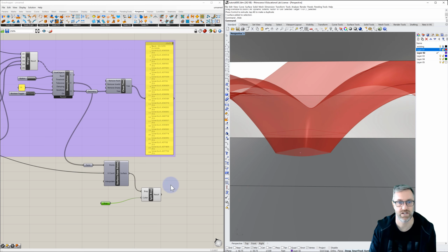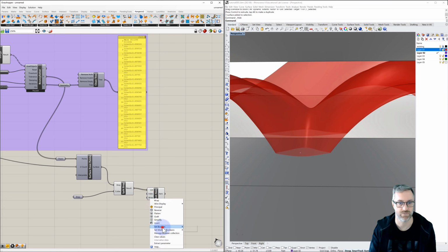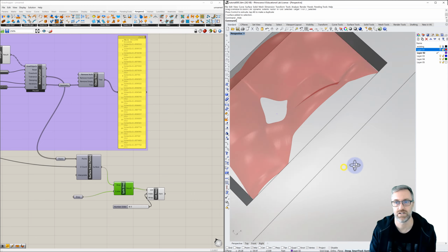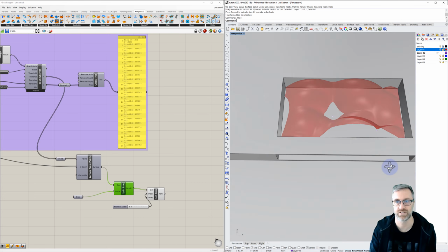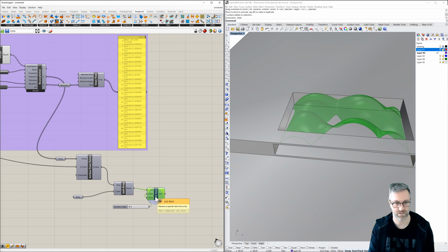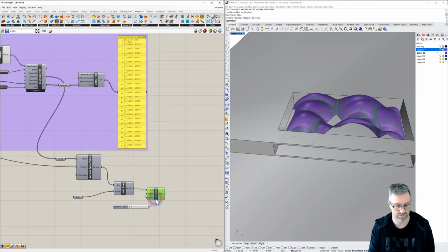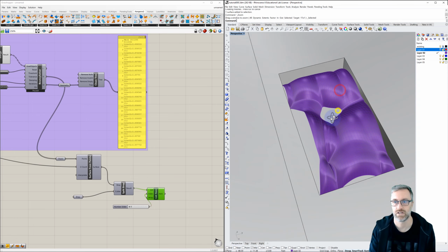And now we can see that it did split it, but our B-rep result has 2 trimmed surfaces. And so let's grab the one that we want, which is list item. And we can toggle between those and see which one we want. A slider with 2 or 3 on there works. We can see 3 is greater than that. And so now we have a NURBS surface that we've trimmed. We've controlled some of those elements. We can bake this now if we want. And we could render it. Like that. And now we can go about our business within Rhino of working with that.